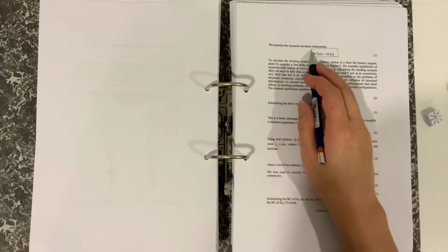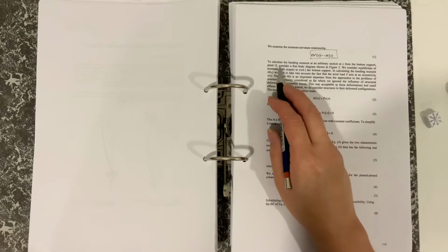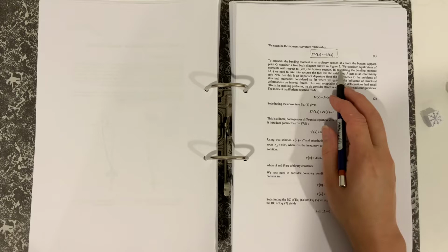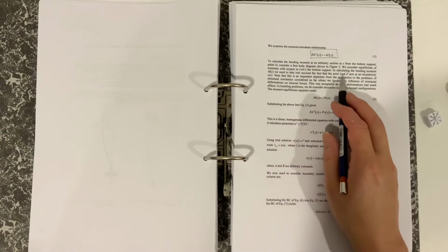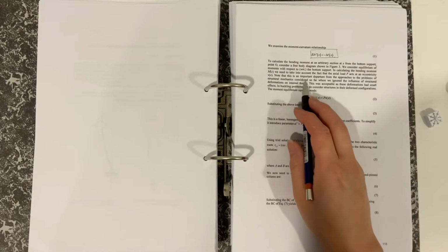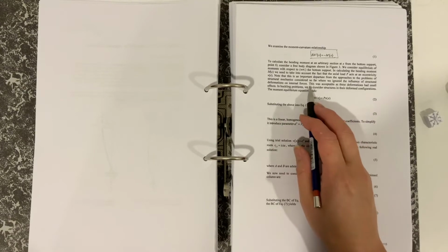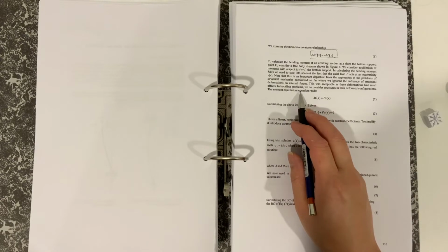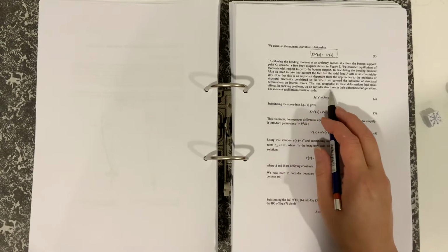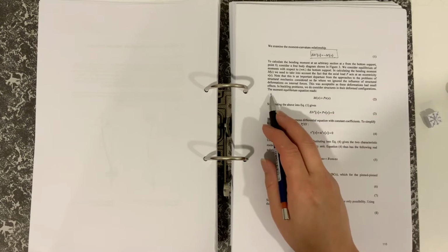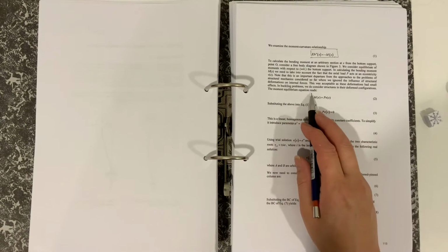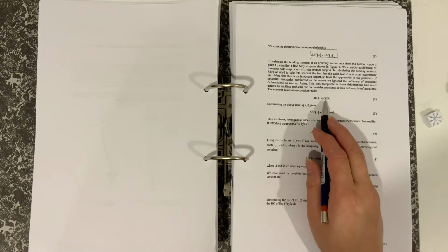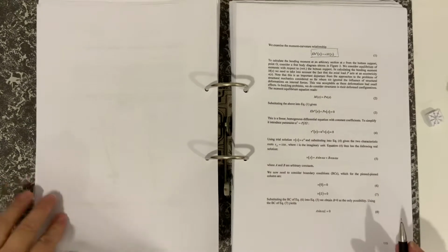So we would go back and examine that expression, and to calculate the bending moment at an arbitrary point from the bottom, we've seen figure 3. Take moments, P has an eccentricity as I've just described, and we ignore the influence of structural deformations on the internal forces. In buckling, we do consider structures in the deformed configuration, and so the moment equilibrium relationship reads as the bending moment M of x is equal to P times V of x.